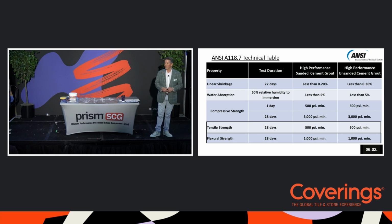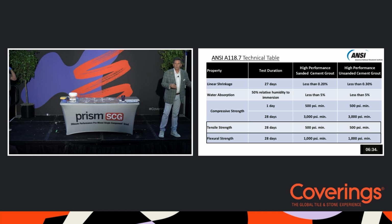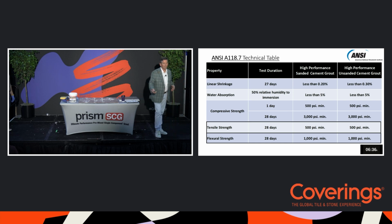This is a technical table from the high performance grout table, and you can see that the compressive strengths remain the same. We can see the tensile is the same, but we can see we now have flexural added to it, and that's 1,000 psi. But let's look at the water absorption here. So that went from less than 10 to 5%. And that's because a calcium aluminate system is a much denser system than a Portland cement. So it lowers the absorption. So that's a good thing because absorption is relevant to staining, right?